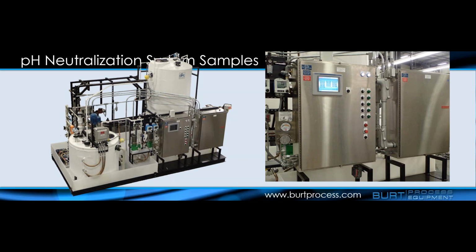So yes, when you get into more pure or low-grade reagents that you're now neutralizing in your treatment system, you definitely need to go to things like stainless steel or PVDF, and you definitely need to have a heat exchanger that can then remove that instantaneous heat of reaction. Otherwise, your chemistry can just boil.